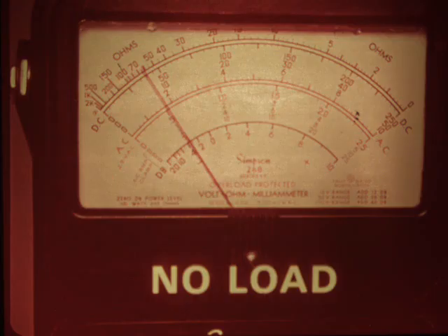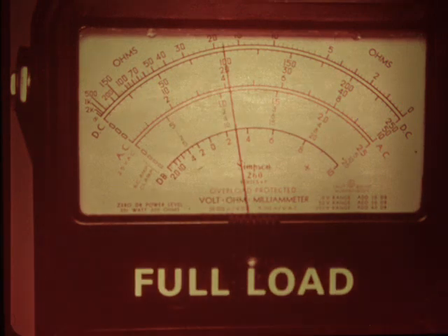Clip the positive lead to the F1 wire terminal and the negative lead to F2. Then read the field voltage under no load and full load conditions. With the generator operating at no load, the field should be receiving about 40 volts. At full load operation, the compounding reactor should step up the field voltage to about 100 volts to maintain generator output. If it doesn't, the compounding reactor is defective and you should replace it.